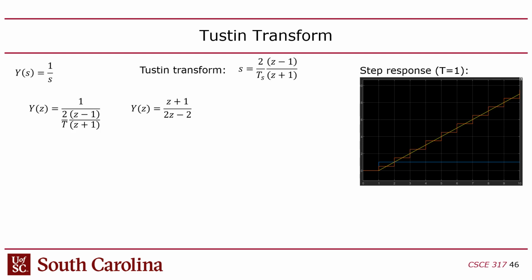Okay, so how do we go from, what if we have an S domain transfer function? Because remember, when you do a physics equation, there's no Newton's laws of motion for discrete. They don't exist. Newton wasn't a computer scientist. All his laws are defined continuously. So if I have a controller that I build in the S domain, because the plant's in the S domain, it has to be, right? The plant is in the S domain, the controller is in the S domain, I build my controller, I convolve them, but now I have to run this on a computer.